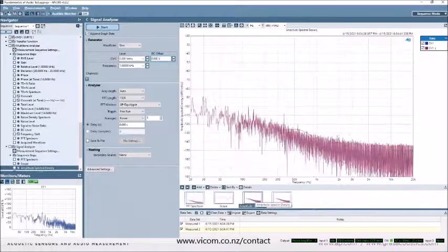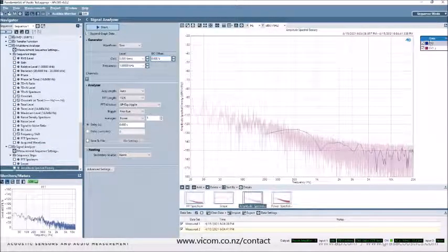If I'm measuring noise, and here it's a little bit hard to see, and I use amplitude spectral density, you'll notice that they're sort of about the same amplitude, regardless of the length. The quick and dirty is this. If you're measuring coherent signals, or you want to extract the level amplitude of coherent signals, use RMS scaled FFTs.